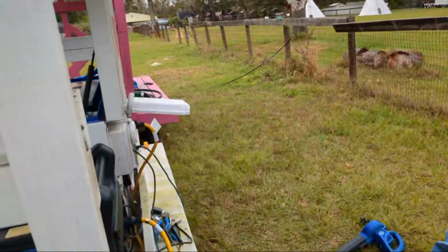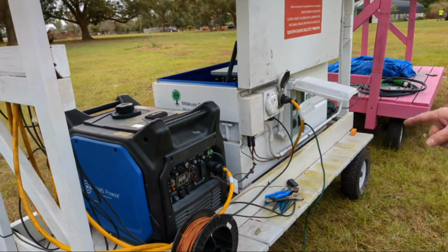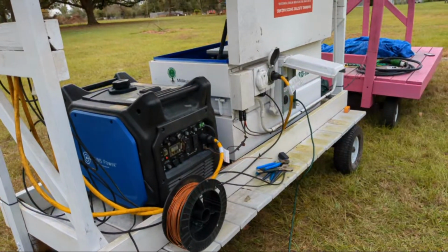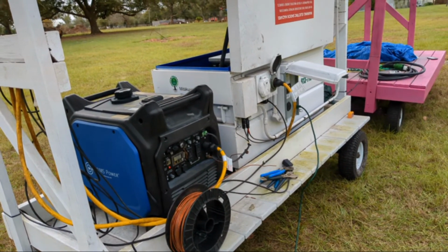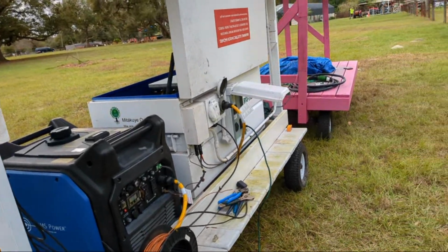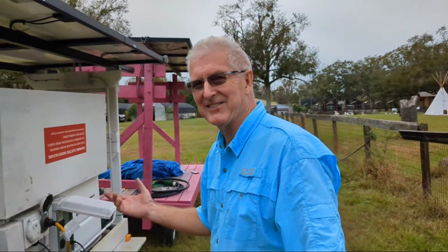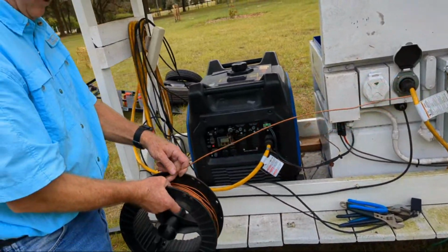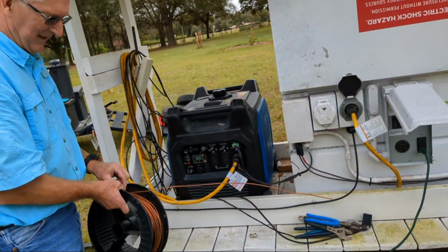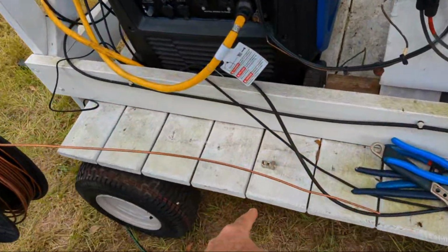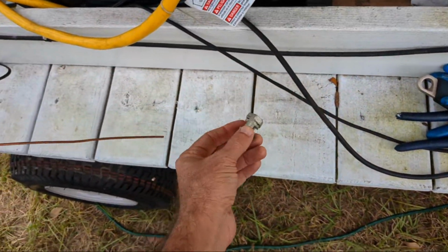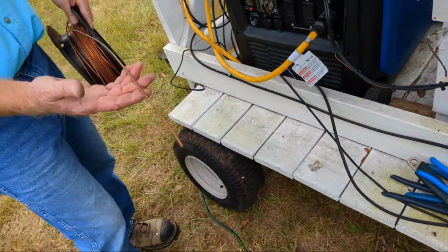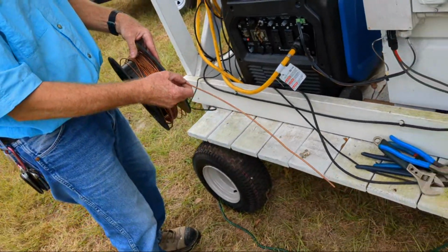Okay. So I don't have a fitting that will fit on that. No? So we're just going to take the copper and drive it into the earth, which actually might be better for a temporary solution. Because if someone does decide to drive away, it's just going to pull out of the ground easily, right? True. And it wouldn't be better just to wrap it around that loop? No, because it wouldn't bond. I need to connect that to the rod, and the rod's too big. And there's no sense in bonding this to another piece of metal. It's metal itself. We might just as well use this number 6.